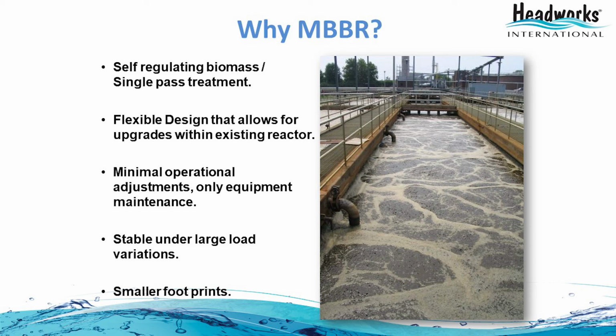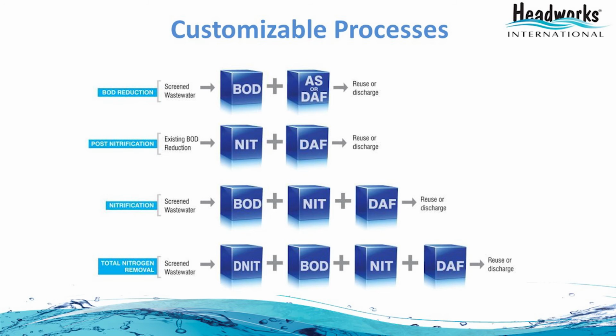Or increase the treatment capacity by a factor of 4. So either way, we can combine those two: increase treatment flow capacity or meet new regulations for nitrogen and phosphorus removal within the same existing tank. So again, MBBR IFAS processes are highly customizable.